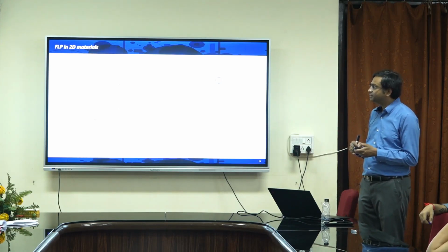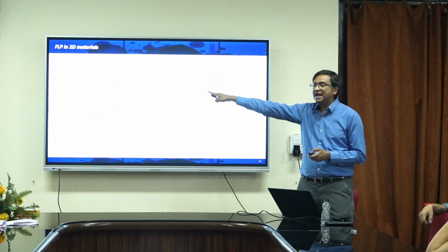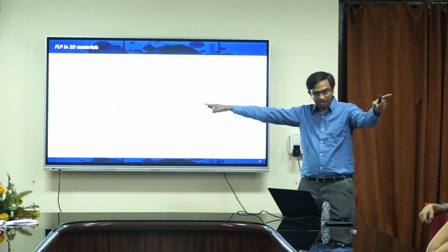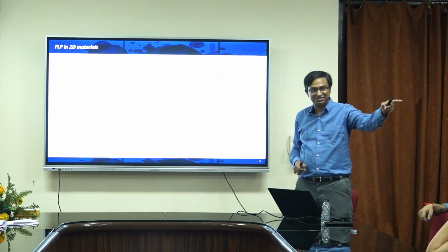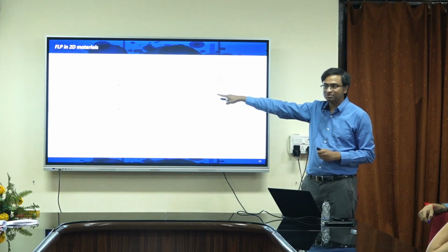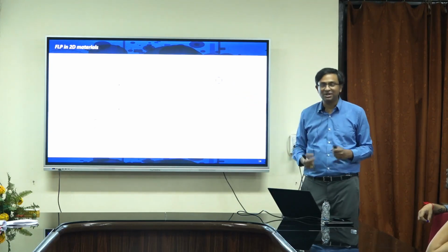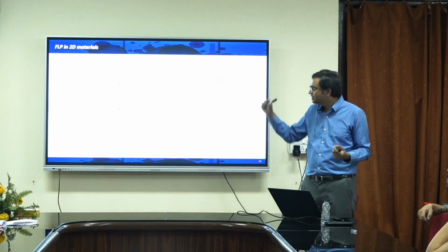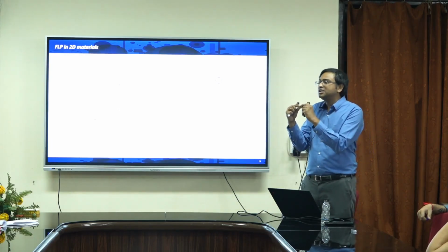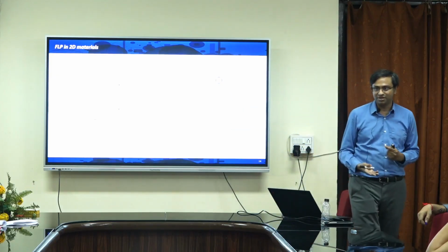And because of the Fermi level pinning, even if you choose platinum, which we thought would give us p type characteristics, you see where the Fermi level of platinum is with respect to MoS2? It is very similar to where scandium and titanium are. So I can change the work function by 1 eV, but in reality it only changes by 0.2, making a p type FET almost impossible for 2D material, for MoS2,